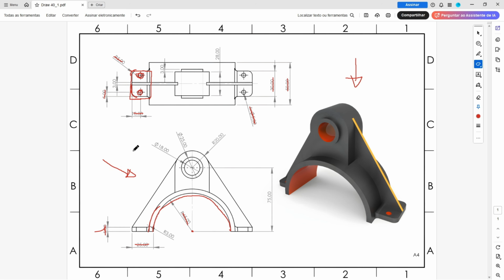And now we will select the front plane again and we'll make this sketch here, this line, and this arc and this line, the both lines are tangent with this arc, and this arc here has 20 millimeters of radius, and the distance between the center of this arc and the midpoint is 75 millimeters.